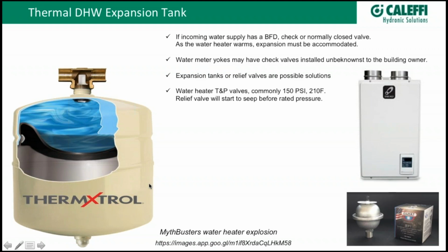So don't try and use just a regular hydronic expansion tank. You'll get rust, number one. You won't have this protection in here. And also you want to have the device in there, the little turbulator, the little orifice that's inducing a little bit of flow through here.